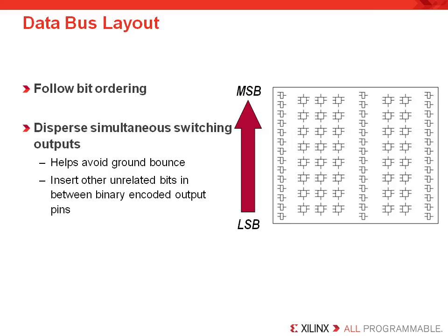This means that binary encoded logic and large data buses should be anticipated early in the planning process. Likewise, this may only mean breaking up a bus between two neighboring banks, but the sooner you plan for this, the less debugging you may have to do later on. So plan your pin out and use the noise utility very soon in the design flow.